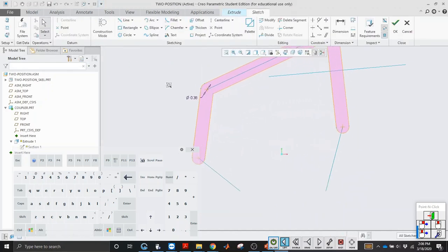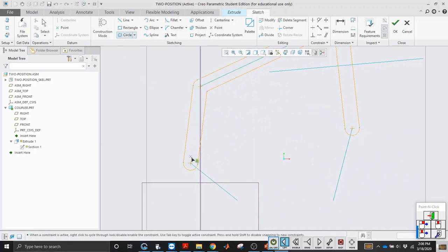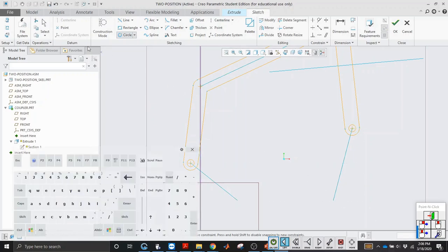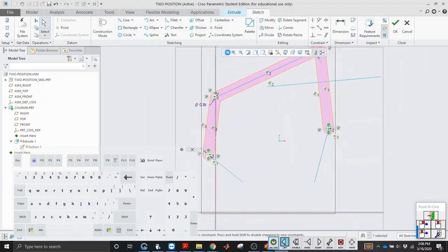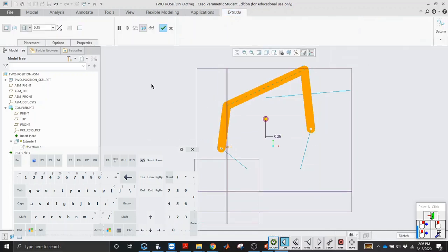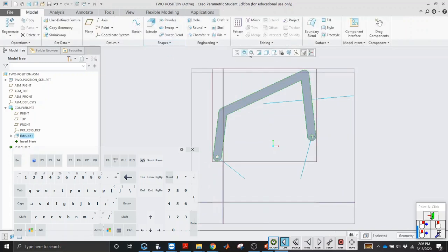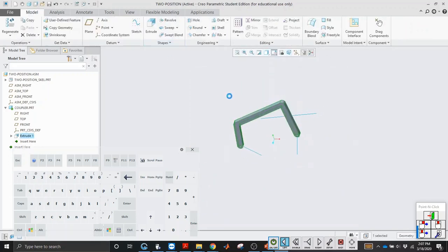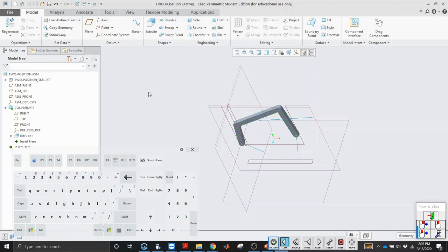You're not going to want to forget this step because otherwise you're going to have trouble assembling. You need bolt holes. And of course, the last one didn't match the size. So a common screw size is 1/8 of an inch. So let's make this a little larger. And we're extruding by 0.25 and we're splitting it. So now if you look, it goes straight through. So there's another thing we want to do.